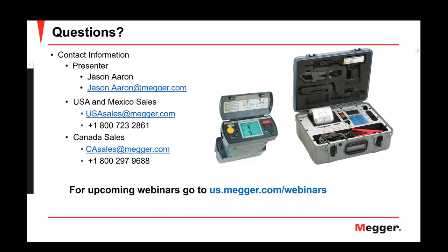All right. Volney, are there any other tests recommended for batteries? What are the equipments required in that case? And what are the IEC or IEEE standards? Okay, so the electrical tests that you can run on the battery to determine the condition of the battery, as Jason mentioned at the beginning of the presentation, are two: the capacity test or performance test, and the alternative test, which is the impedance test or the ohmic value measurement.